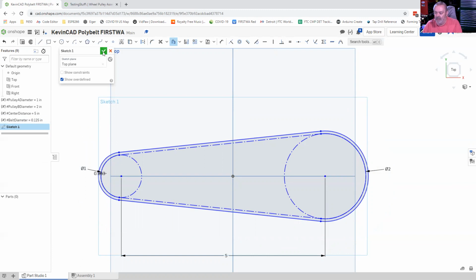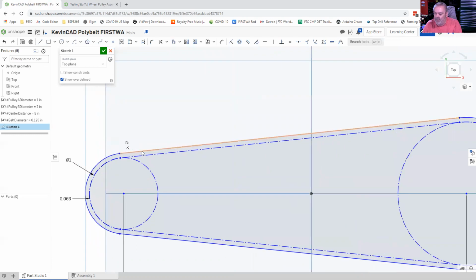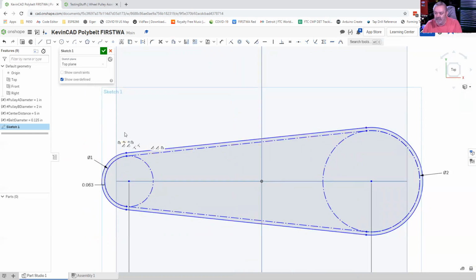So I'm going to do a couple of things here. I'm going to turn off the offset tool. I'm going to move a couple of dimensions. Move this guy out so that we can read it. Okay. So I no longer need that circle or that arc to be anything more than a construction line. So I'm going to set those to be construction lines. That way they never get in our way. So we have construction lines, and then we have a path. This is actually called a sweep path. And that's what we've designed here, a sweep path.